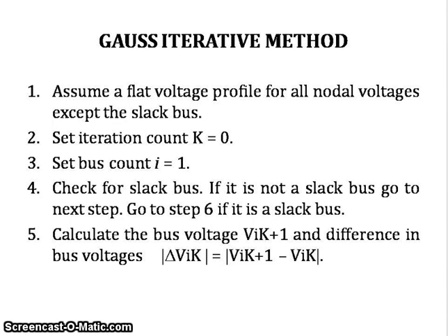Hello everyone. As discussed in the previous videos, the power system comprises many buses, many generators, many loads. So there is a requirement to compute active power, reactive power, and voltage profile in each bus, so that if any load exceeds or if any generator supplies less active or reactive power, we can see that there should not be any contingency in the system. To find that, as we discussed, load flow studies are important.